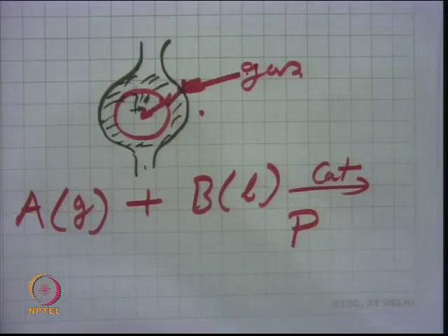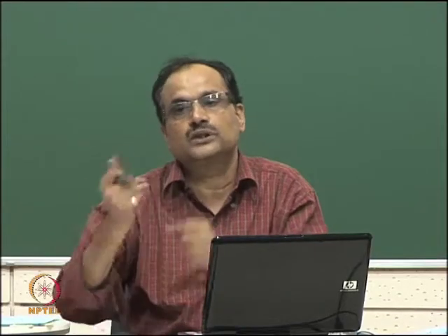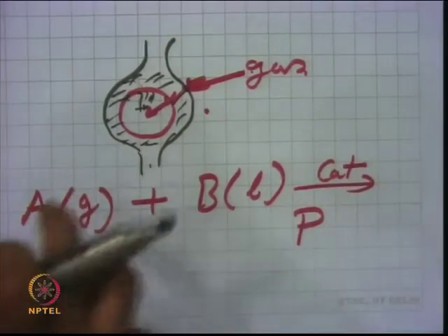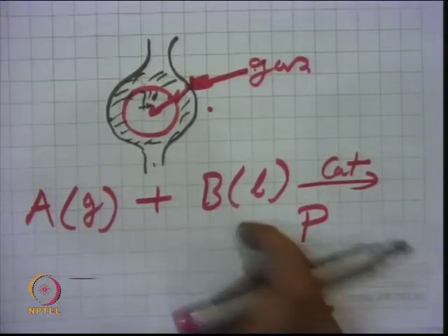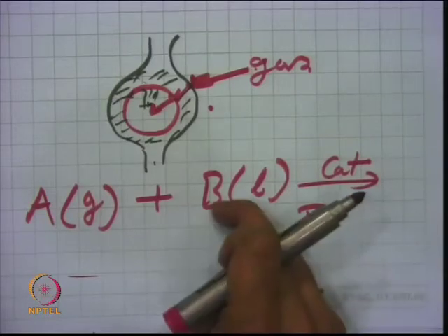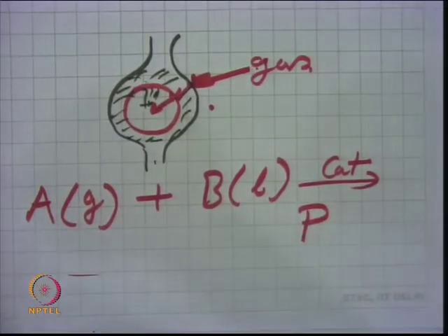transfer of this hydrogen gas from the diesel liquid, through that to the surface of the solid, and then to the pore of a catalyst where already some diesel is present, and then these two react like this, and the sulfur which I am talking about here. So, when I say gas, it is your hydrogen, and when I say this B liquid, it is some sulfur compound, benzothiophene, dibenzothiophene or mercaptan, and then it converts into hydrogen sulfide basically. So, that comes out of the pore, which is a gas basically. So, this is what we look at here.